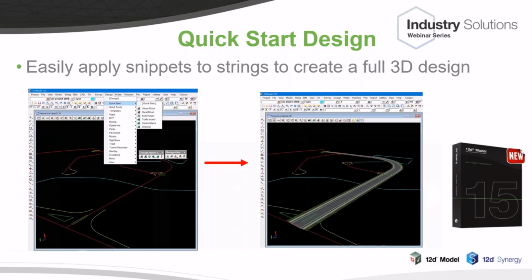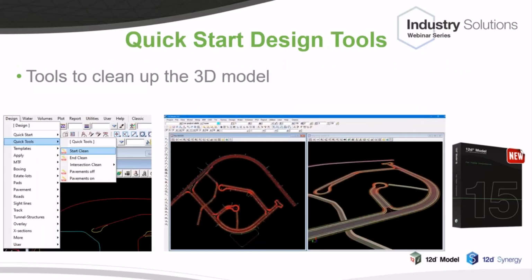There's also quick start design tools which allow you to clean up those sorts of things. So you can go in there and clean across an intersection, things like that to make it easier. But you also can turn your pavements on and off of being produced, because sometimes you don't want all the 3D pavements, you only want the strings. So again, the choice is there. We will be having a webinar on this since it's a very, very useful tool.